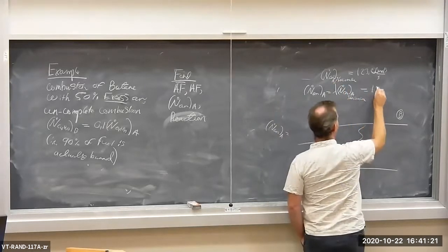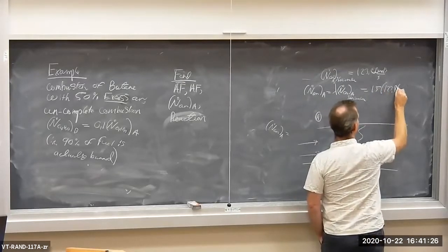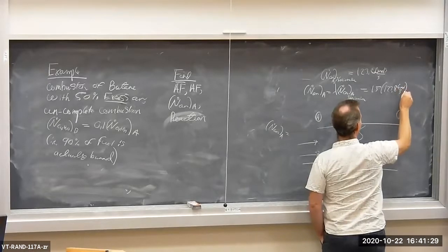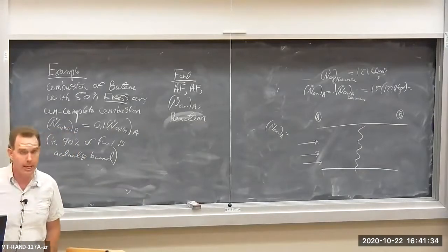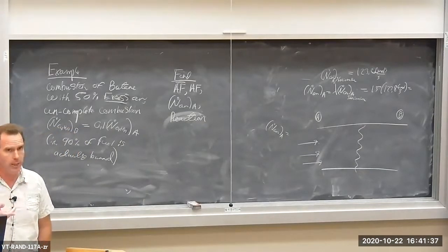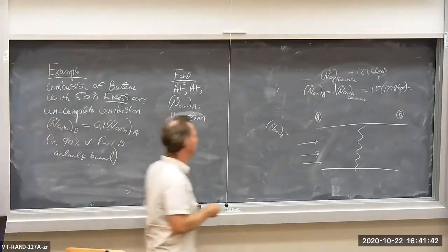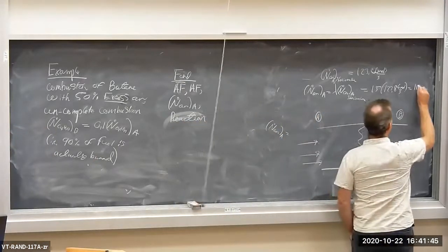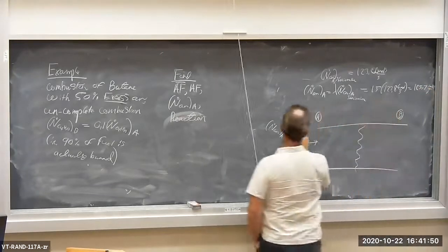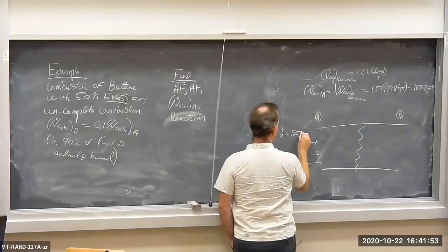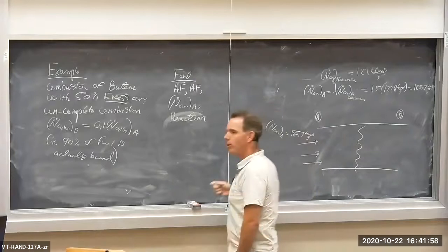So that's 1.5, 50% more, times 123.8 kilomoles per second. And we get an airflow rate in this new excess lean combustion, more air than fuel than we need, so it's lean combustion, of 185.7 kilomoles per second. Okay, so that's our new airflow.